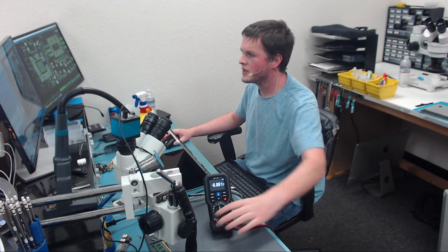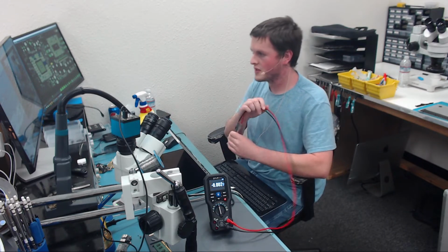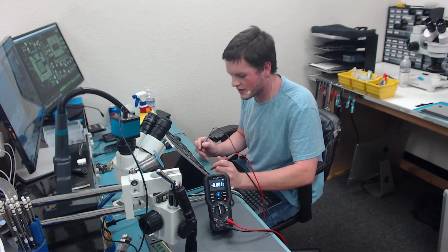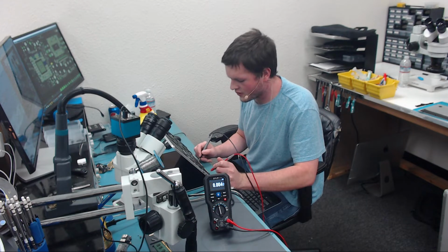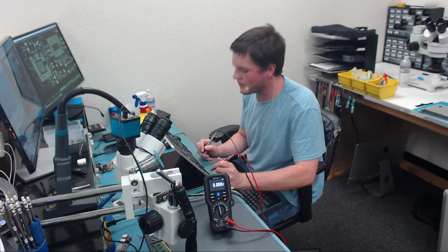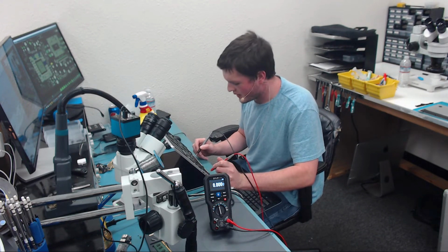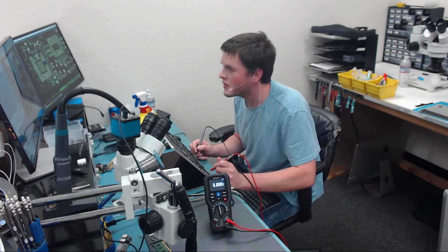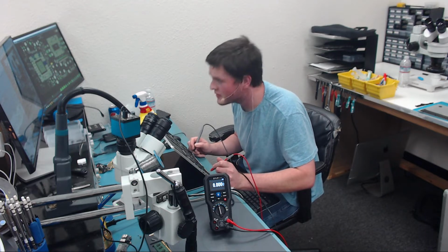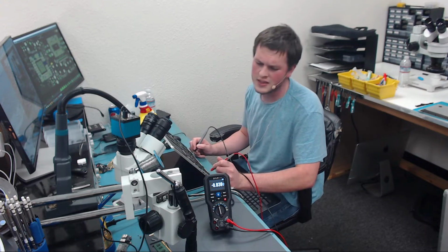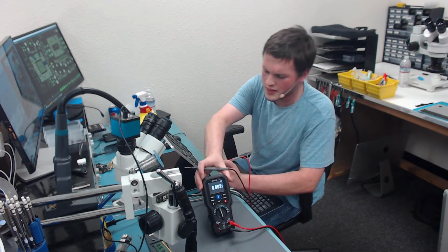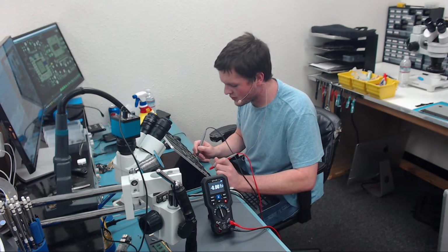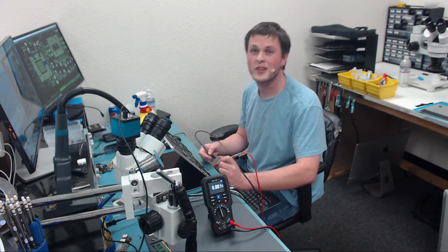You can see that, hopefully. We have no voltage, obviously, since it's not touching anything. Let's measure GPU vCore. Notice we still have 0 volts. We have nothing on that coil. We have nothing on that coil. We have nothing on that coil. And this should be CPU vCore. We should have some voltage there, and we do. The CPU, when it's not under load, is going to be 0.8. So we have no GPU vCore. There's no power going to the GPU, and therefore it cannot work if it doesn't have power.